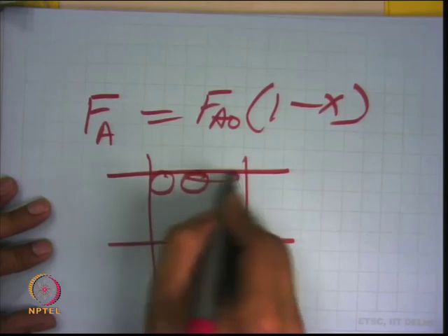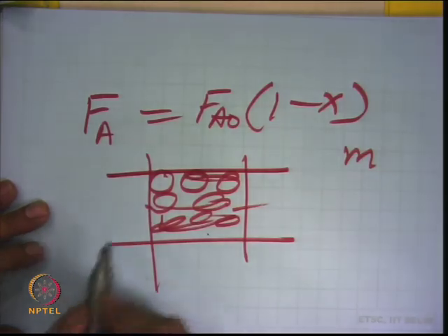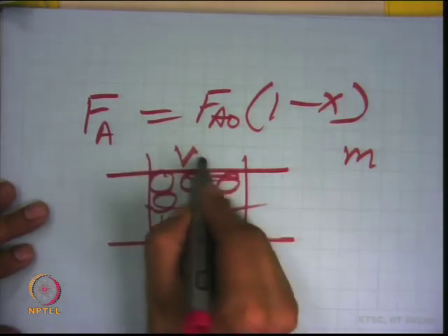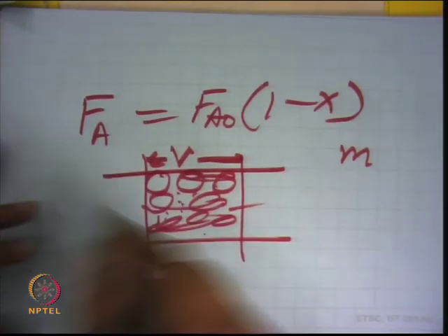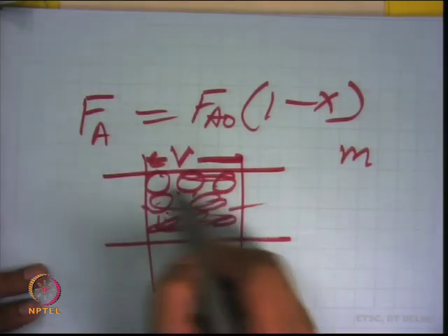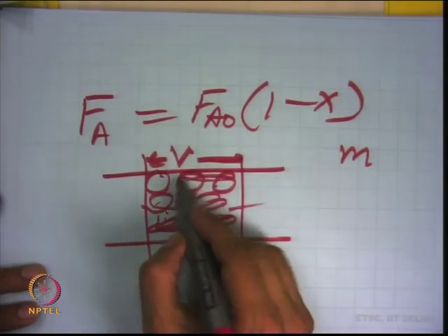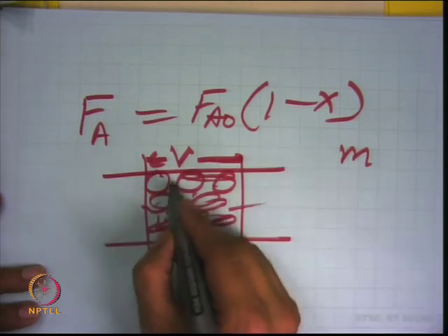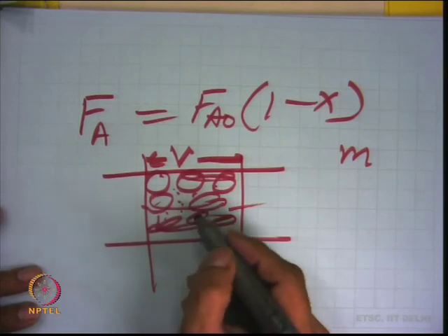These terms should be very clear to you, because sometimes different terms may be used here. When this catalyst has been placed in the bed like this, there is a mass of the catalyst, which is m, and the volume of this is the volume of the bed V b, because it includes the voids, the gaps. So, the actual volume of the bed is nothing but the volume of the catalyst plus the voids, which we define as epsilon b, basically the void fraction of the bed. The void fraction of the bed you can define in terms of the volume of the bed.